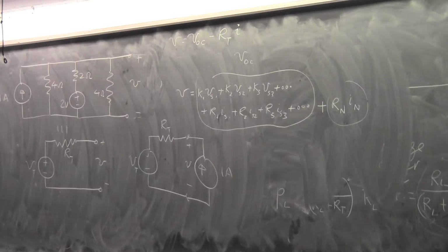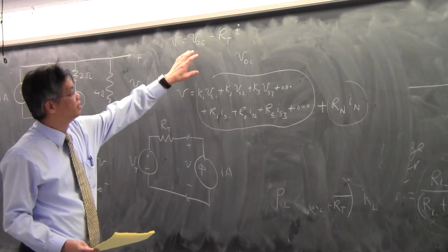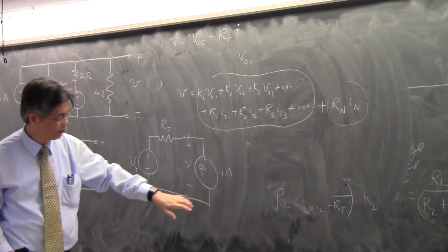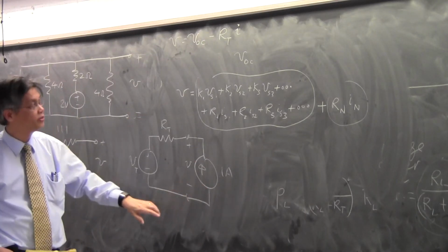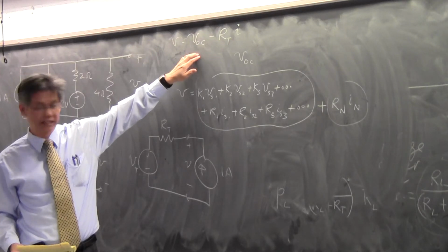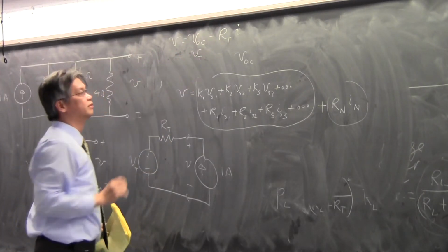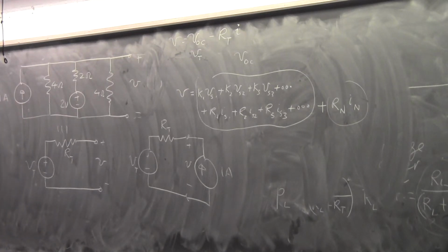Okay? So this is just that model that we have over there. That voltage is always equal to R Thevenin times I. And you can write down your Kirchhoff voltage law on this loop, and you find that this equation is automatically satisfied when V open circuit is just V Thevenin. That equation is automatically satisfied if you invoke Kirchhoff voltage law on that loop over there.